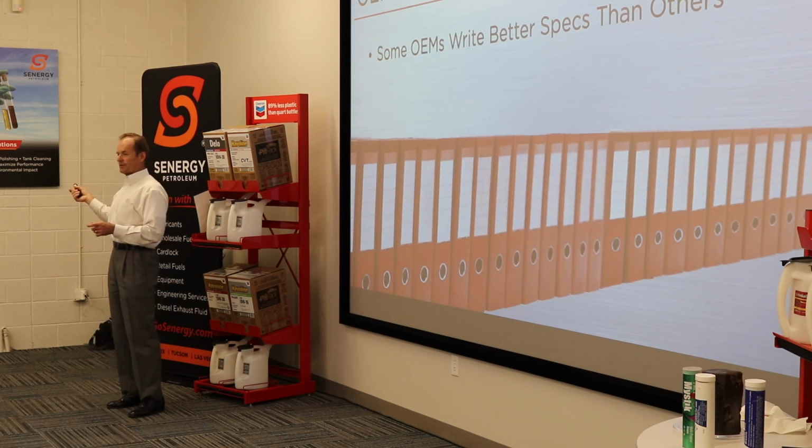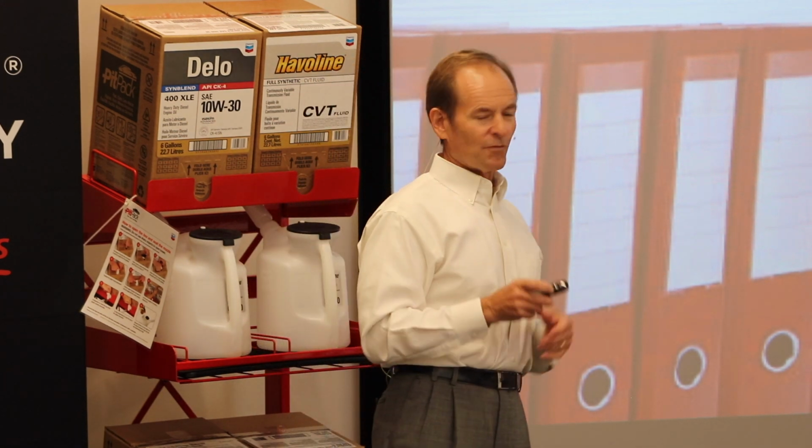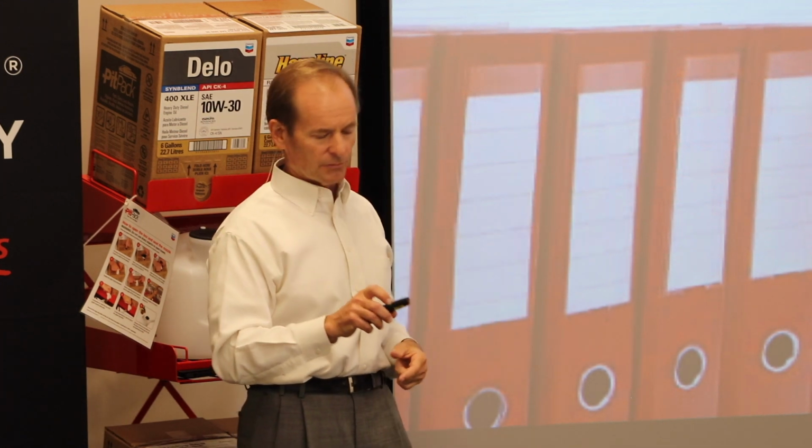And that's why I'll open a manual from a piece of equipment manufactured in 2016, and it's recommending greases that went obsolete in 1974. Okay? That sort of stuff happens often enough. So pay attention. Hopefully I've given you enough knowledge to maybe even spot something in your manual that doesn't seem right. Be aware of contradictions. I've seen this in the OEM recommendations, that there are contradictions in what they're saying or what they're recommending or what they're asking for.